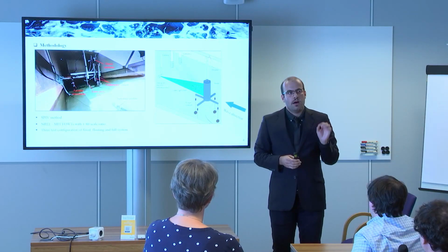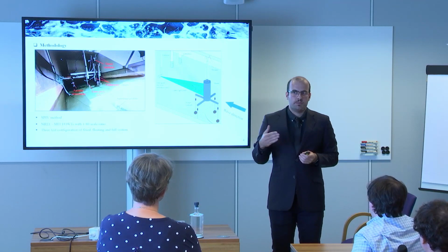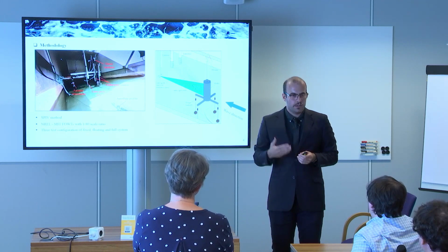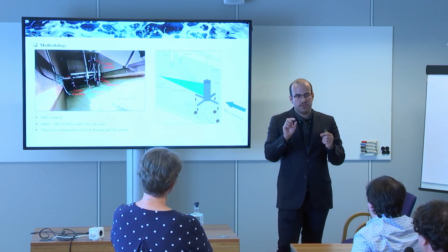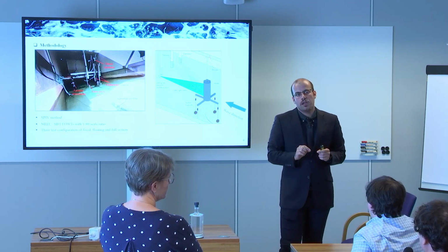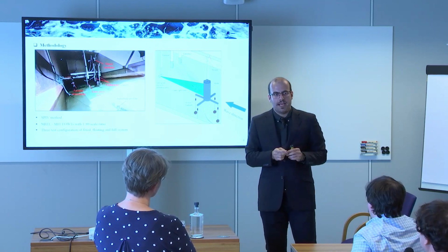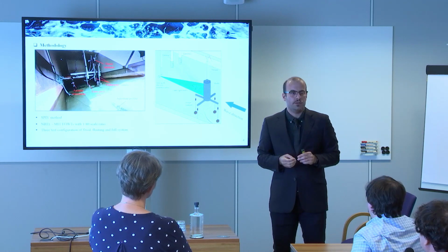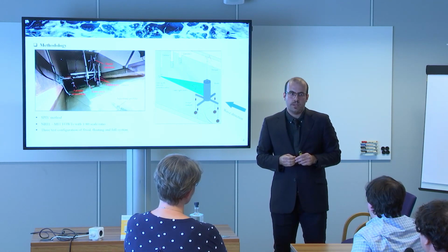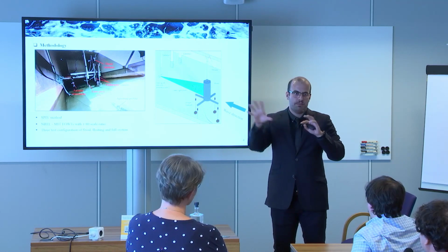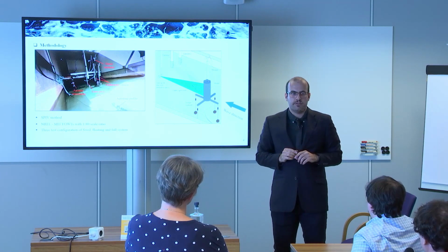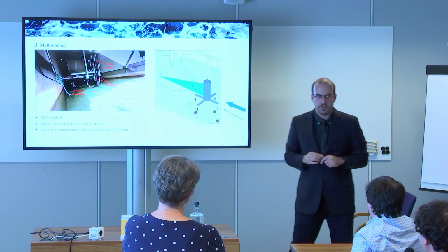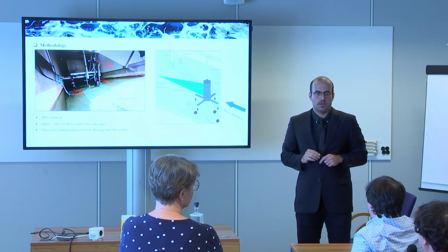So the post-processing was based on the ITTC. I remember that I used a post-processing method based on cross-correlation with decreasing window size. The initial window size was 64 by 64 for the first pass, and the final pass was 32 by 32 with 50% overlap in both X and Y directions. And a Gaussian fit was used in the post-processing method. Okay, thank you. No problem.